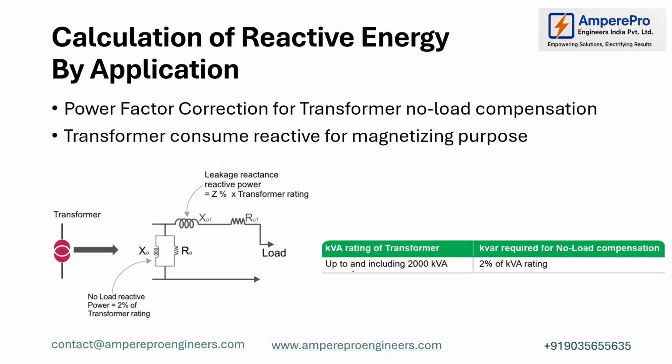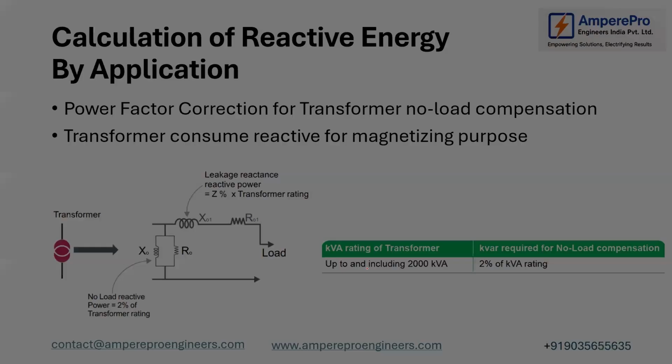Even when the transformer is not connected to any loads, it will consume some reactive power, because the transformer core needs to be magnetized. So for that, typically they will add one small capacitor, which is typically 2% of the transformer kVA rating. You can go with that.